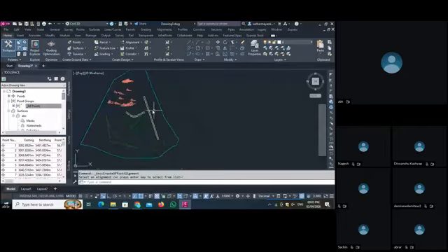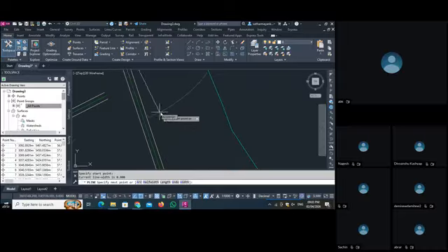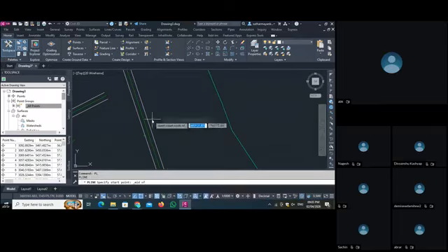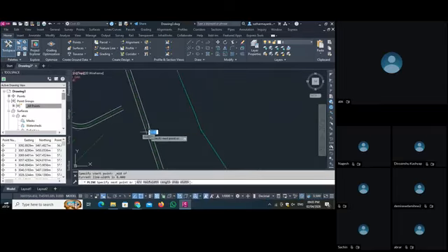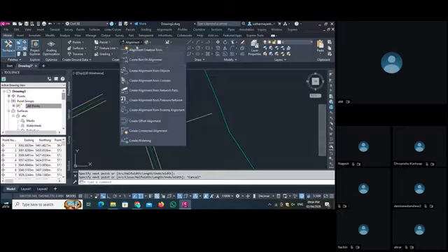So let's create road number 2. Let's create the polyline. I select the polyline from C, PL, enter, and I specify that I want a midpoint. So this is the polyline I created. See, now this is a polyline, not an alignment. What I do, I convert it into the alignment.